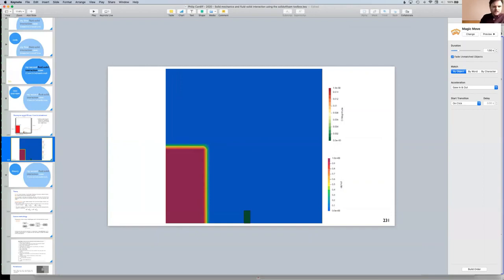Thank you very much. I'm curious if it's possible to simulate the movement of an elastic body and a rigid body simultaneously, and how to choose. That's a good question. Not that the other questions aren't good questions, they're all good questions, but it's one that I have to think about. A brute force way to do it would be just to set the stiffness of your rigid body to a very large number, and in effect it will become a rigid body. But that isn't maybe computationally efficient.